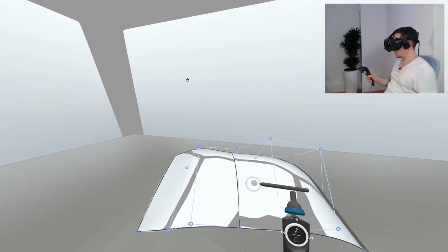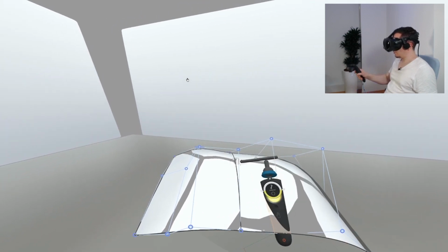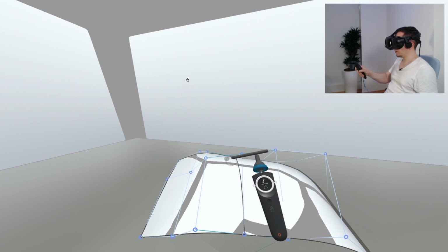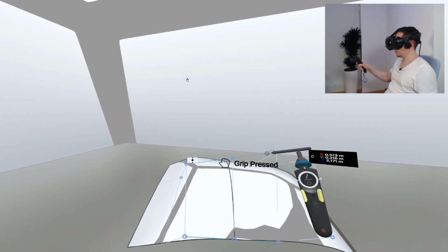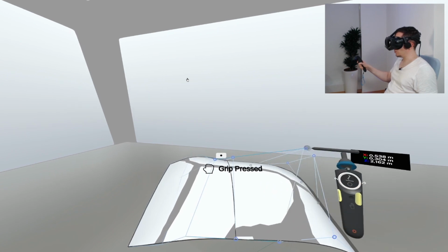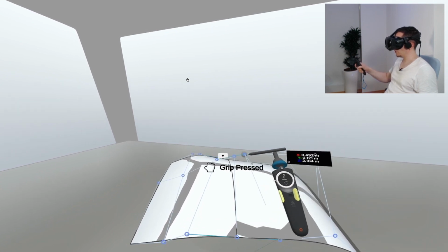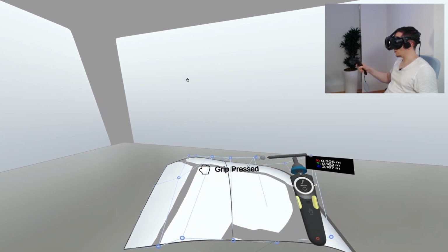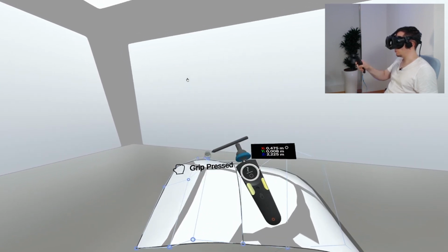So to repeat things, hover the connecting curve, press the mode button, turns on this kind of continuity. Hovering it again, pressing it again, goes to this one, so the non-symmetric G1 combination. And pressing again turns off this feature and you can freely move again.